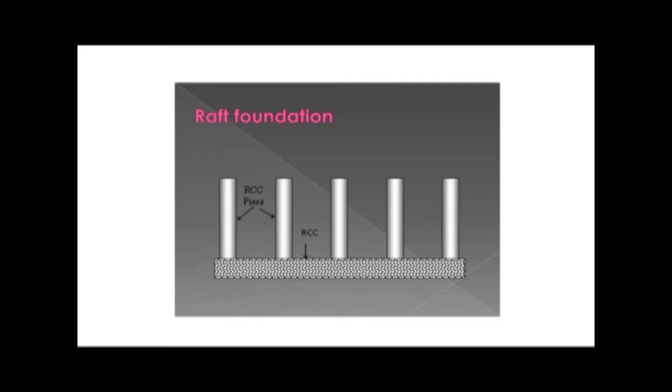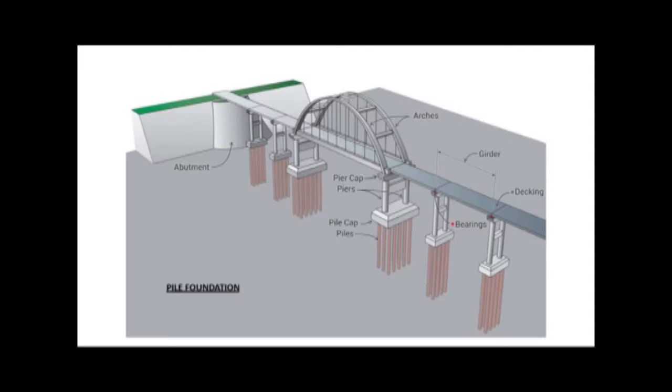attached with the shuttering, and in this shuttering we pour concrete, and as the load increases it sinks and the extraction from the central muck is made with clamshells, etc., or it could be extracted manually. The central muck could be excavated manually. After that the caisson sinks down, and we lift the shuttering up and up, and as we go we pour the concrete into it.